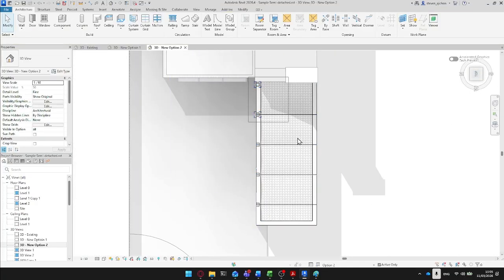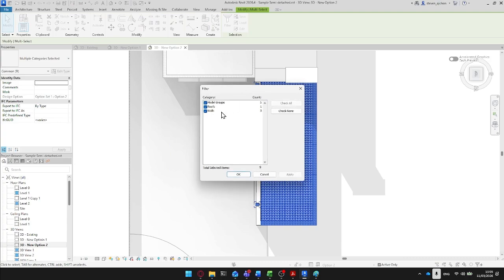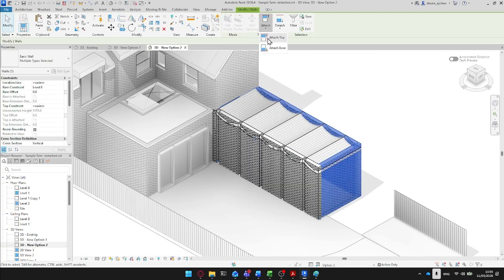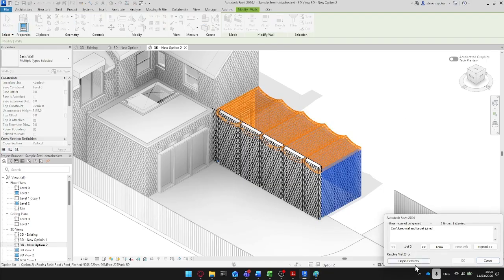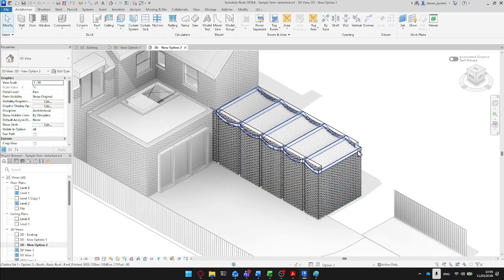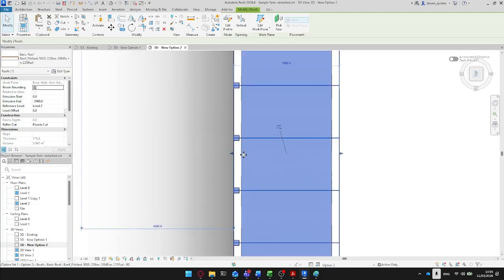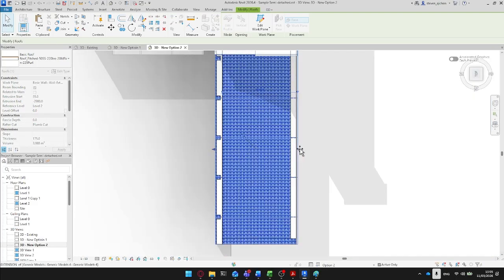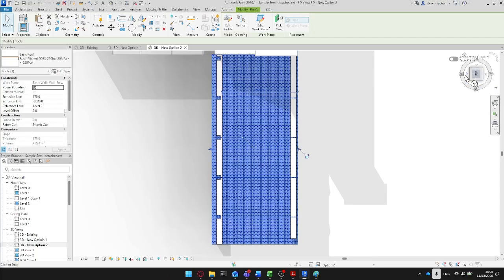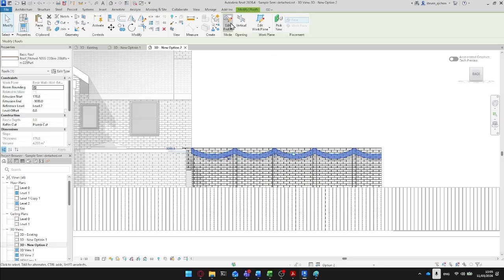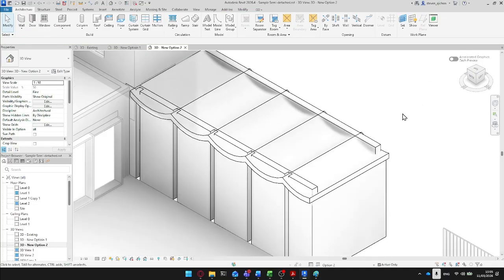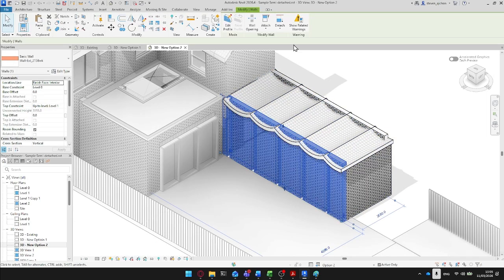We'll just select the walls. Again, the filter tool helps us here. And attach these to the roof, which I think needs to be slightly bigger. And we'll give it a small overhang. And we'll attach this wall to it.